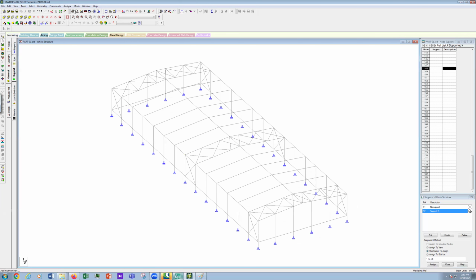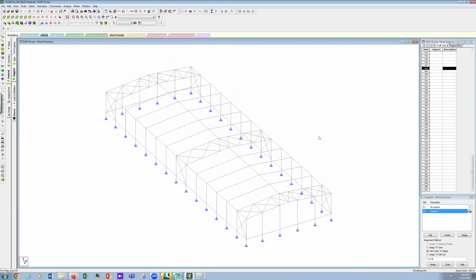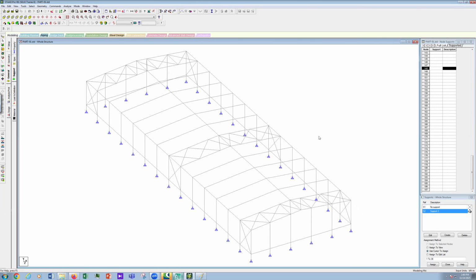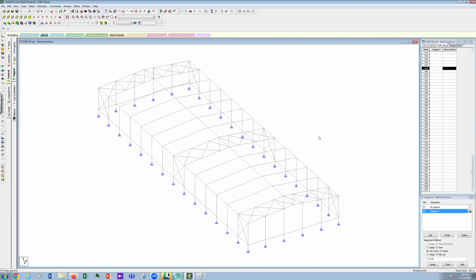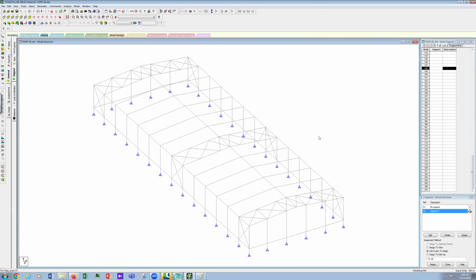So this is a full modeling of an industrial shed. We have drawn RCC column, grade beam, steel column, rafter, stay member, and bracing. We have considered cable bracing or rod bracing here. You can consider pipe bracing or angle bracing, or any kind of I-joist, whichever as per your design choices. So here is our first lesson.